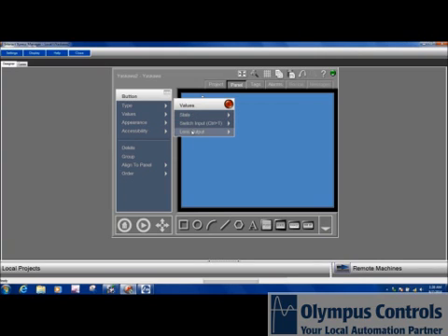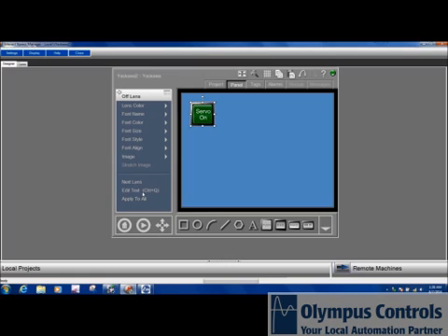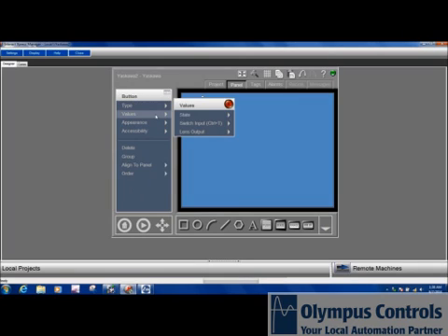I want to also change the appearance. I want the off state to say servo on. And I want the next state, when the servo is on, to display servo is on. Now, I have the ability with a push button to not only give it a switch input, which reacts to the operation, if I'm pushing the button in or letting the button out, but I can also change the status of what the lens is displaying.